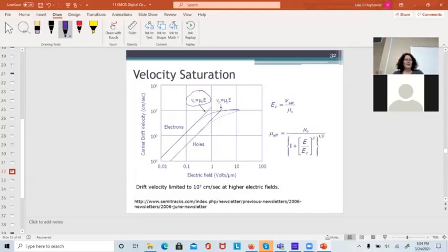So at that speed, remember, the electrons are not moving in a vacuum, they're not moving in free space, they're moving through a solid. As they move through the solid very rapidly, they're more likely to hit something and lose momentum and bounce back and go in another direction for a while, and the electric field will kick them back out again. It slows them down. So this is what's happening here, a semi-relativistic effect, limited by bouncing things off the crystal.